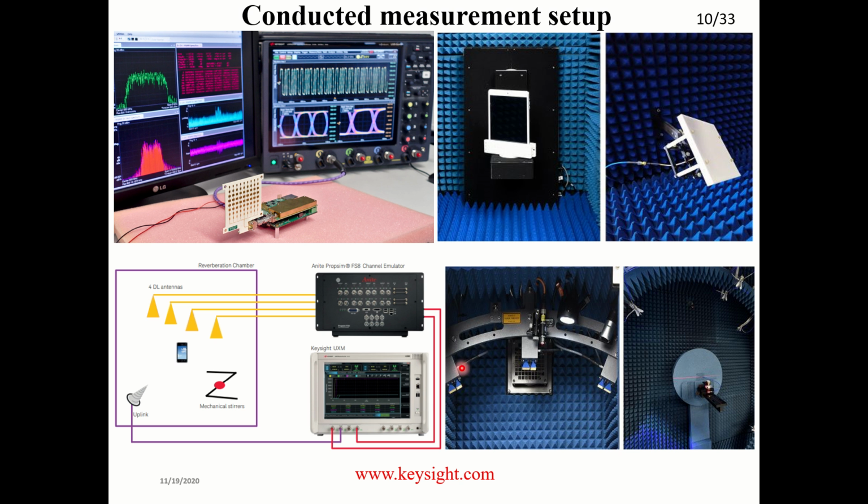And you can see that for protocol testing, they use a combination of conducted and radiated mode setup. Here, node B will be connected. Actually, there are two modes available: signaling and non-signaling modes. Signaling mode is the real-time scenario with fully over-the-air measurements. In non-signaling mode, node B will be connected to these antennas as well as the device.